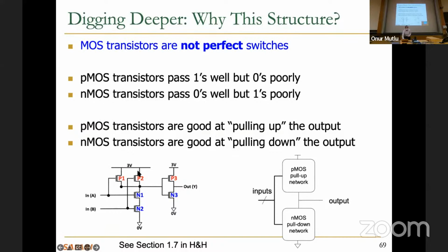Only one transistor needs to be turned on. They could keep adding parallel transistors, 10,000 of them, let's say, I just made it up. You have to go through only one transistor to pull up the output. But if the transistors are in series, you have to go through two transistors, and two transistors need to turn on, and the wire is longer, as you can see, so that the output, or this intermediate output, gets connected to the lower voltage in this particular case.